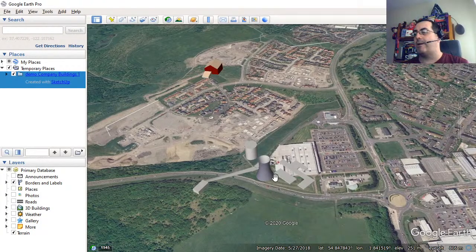Once you've got a correctly geo-referenced map, and you put the geo-referencing into QGIS and geolocate your maps properly, then you take the map and you produce the 2D line work. Then from the 2D line work you bring that into a package such as SketchUp or some other 3D package, there are many of them, and you add the detail to those square boxes, and then the square boxes are saved back out into a format suitable to then be loaded into Google Earth.